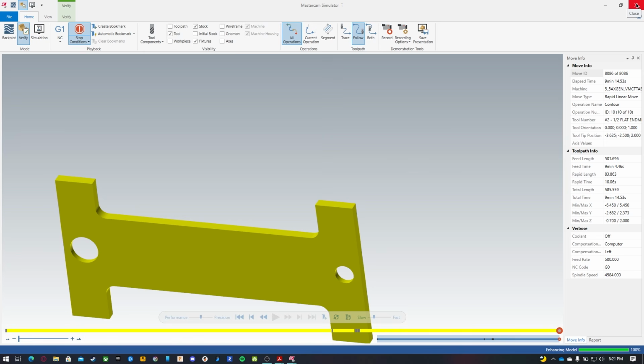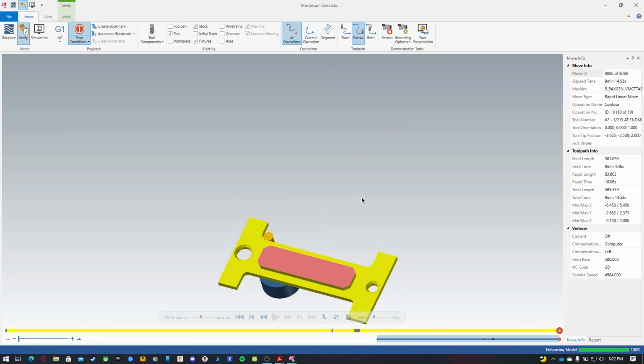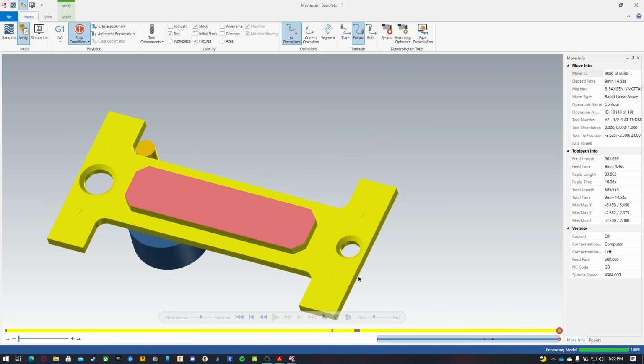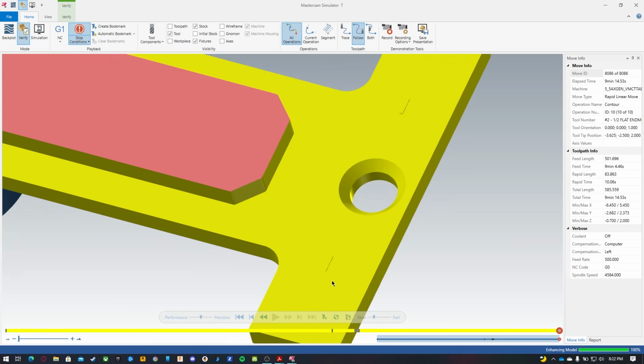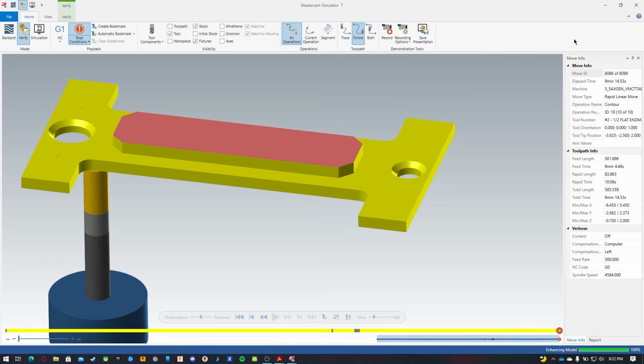So an easy way to do it would be to orient our planes once again and set it up so that we can cut these two sides, flip it over, and then cut with the tool sitting out like this. Now this is what I was looking at, is we have some little cusps for our pocketing that were not cleaned up by this outer contour.